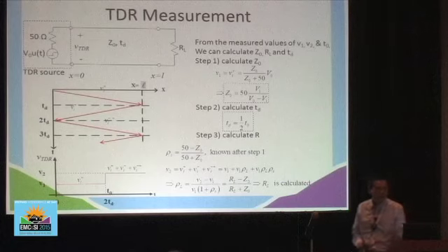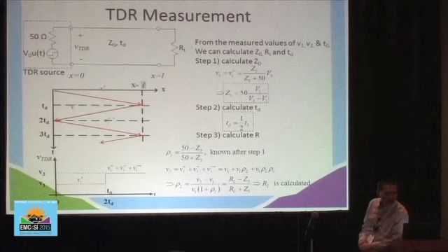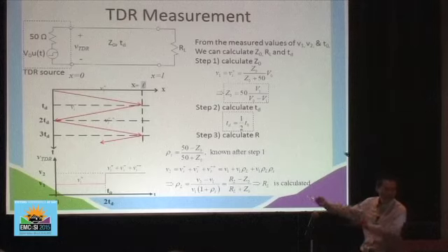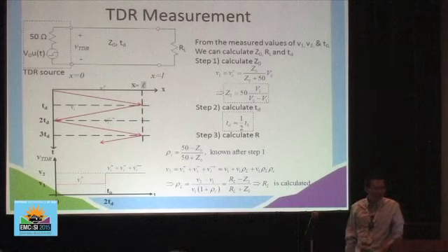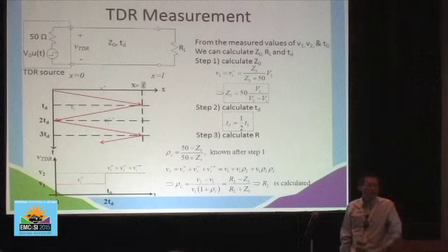Yes, sir. When you said in the bounce diagram, it reflects back. Yeah, because of discontinuities, because of the load. This load is not matched with this impedance, then it will bounce back. If they are matched, you won't see that reflection. Whatever continues on... So when you have the bounce back, that's the reflection loss, and then whatever continues on is your insertion loss, or is that how it goes?